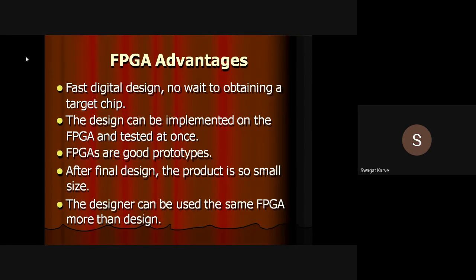Okay, FPGAs are good prototypes. If you want to design a new circuit or a new complex digital design, then FPGAs are good prototypes. Why? Because it is reprogrammable many times, right? If your design is faulty, or there is an error in your design, you can reprogram that FPGA and go for testing again. If you again find some flaws, you can modify your design, reconfigure that FPGA again, and your prototype is ready. That means these FPGAs are good for prototyping.